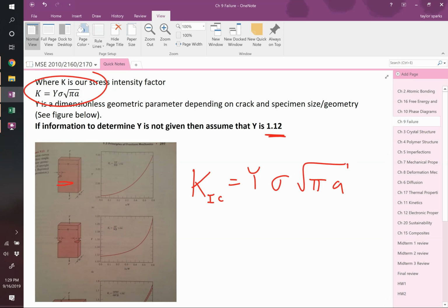So this is really interesting. It's sort of like a seesaw. This equation, think of it like a seesaw. This is a material constant. You can look up for any material you want what its fracture toughness is, right? And if any combination of things on this right-hand side, when you plug them in, is larger than the left-hand side, then the stress locally, at least in some point of your sample, exceeds the critical stress intensity, and therefore it's going to fracture, right?